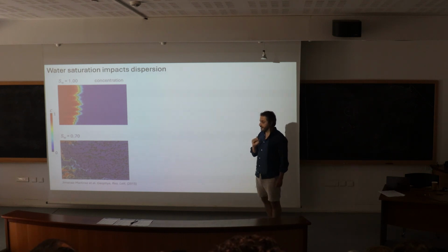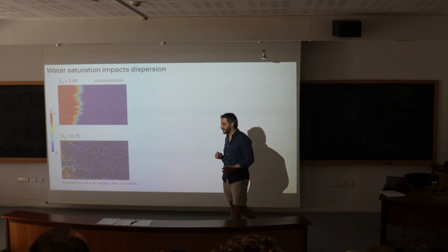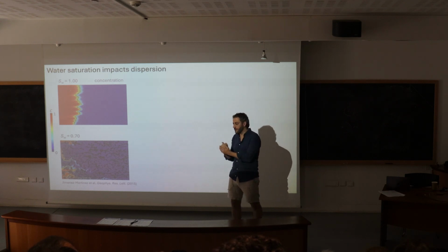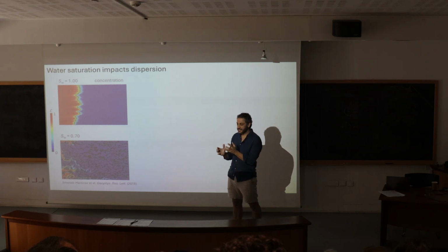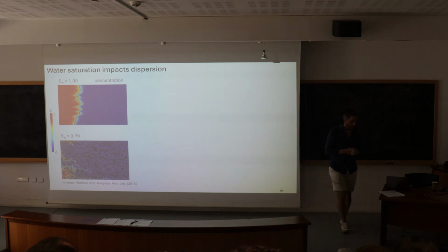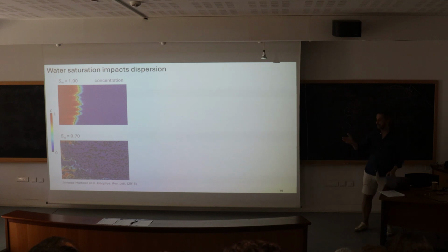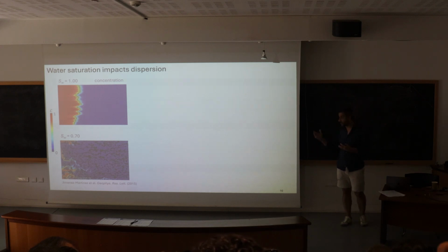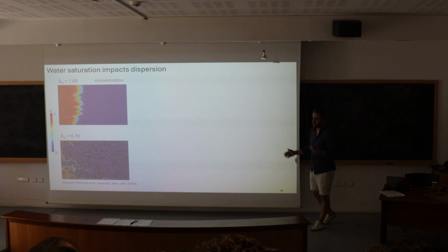It's because in hydrophilic media the interface is somehow protected. Close to the interface, because of capillarity, you always have low velocities. So at the end, if it's slip or no slip, it doesn't matter too much. It matters, I agree, but it's how relevant you want to make this process. If you go for the global reaction rate in the image or in the entire experiment, the impact is minimal.